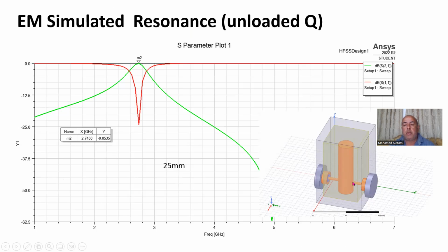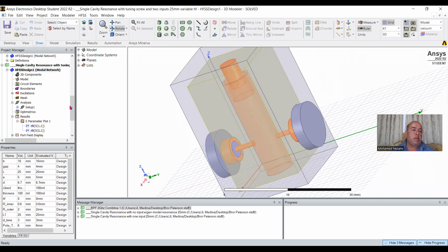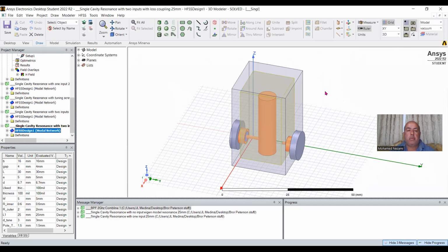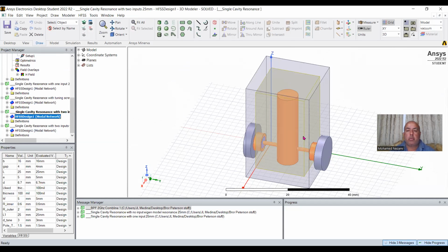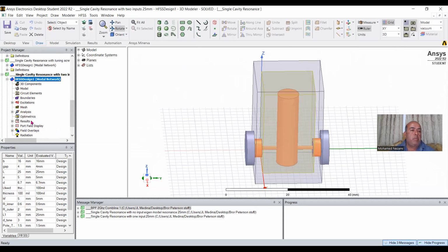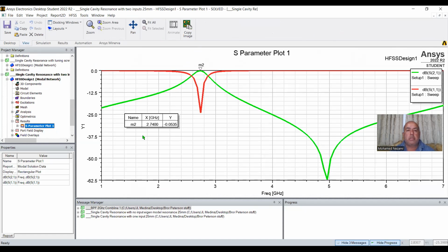You hook it up together, and once it's loaded, you want to make sure that it resonates correctly. So we can come in here and say we want to look at not this one. This one's lightly coupled, but here is this one, where we put a single resonator, and then we run the simulations and check where the Q is. In this case, 2.7.